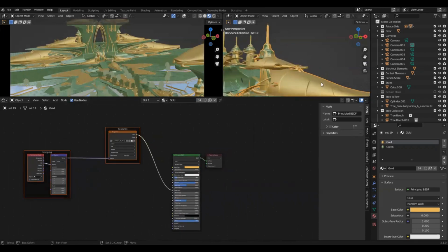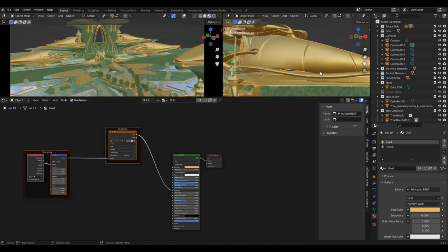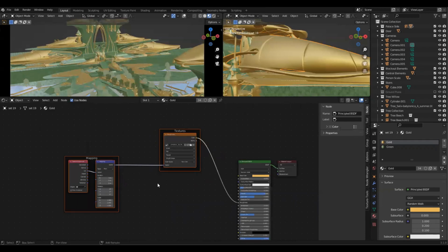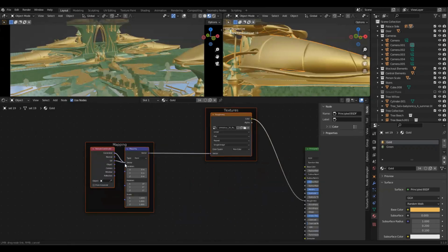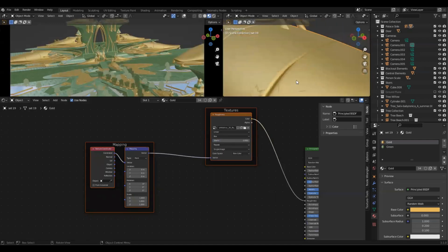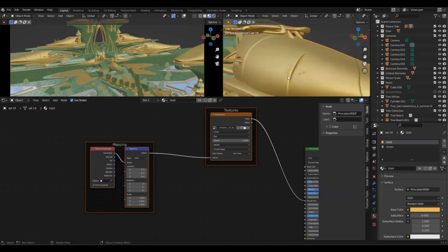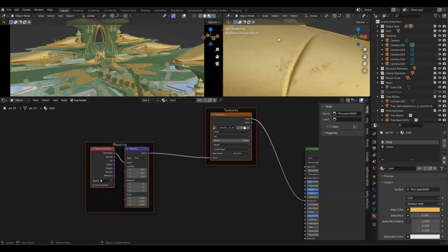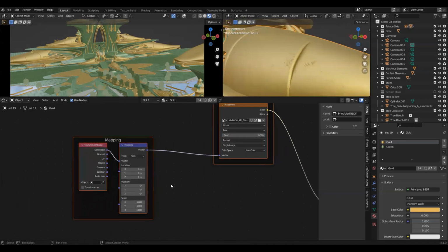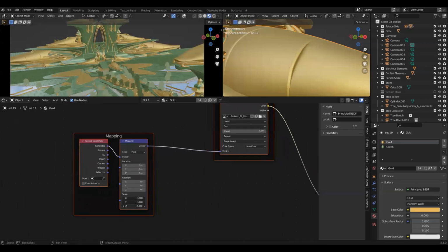And so all it's doing is adding a roughness, which is basically the reflectivity of areas. But we do need to switch this back over to generated, just like we did, and then switch this map over to box. Now we should be seeing something on here, and all that map is the roughness, right? So this area should be all shiny, and then there should be a little bit less shine where these scratches should be. And we should be able to adjust the scale on that as well. Let's just try something like that for now.